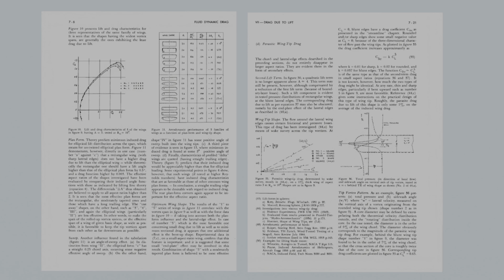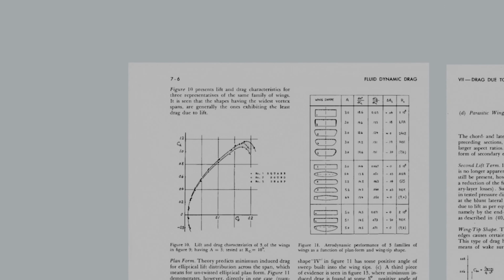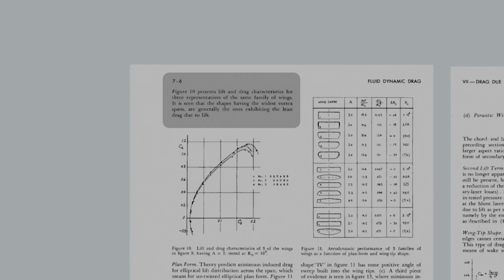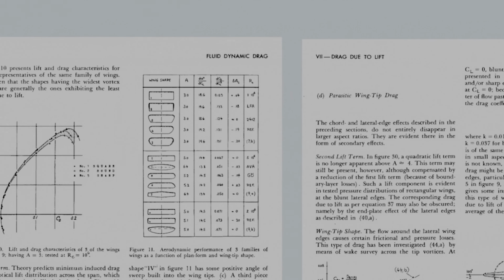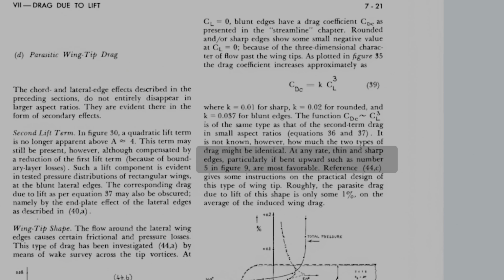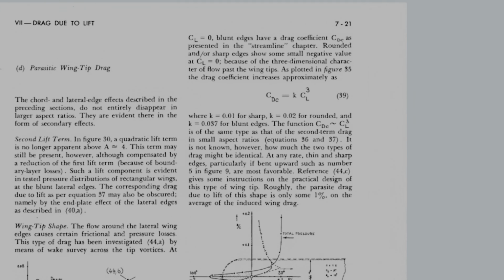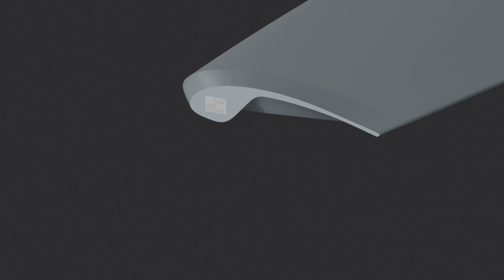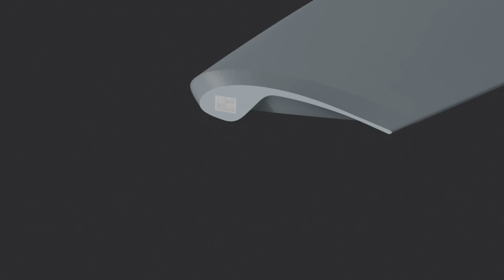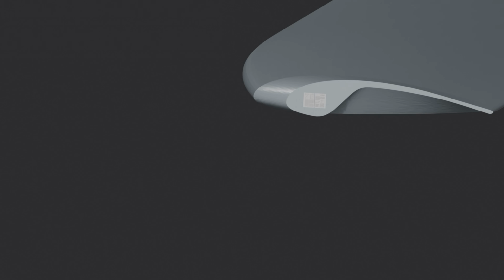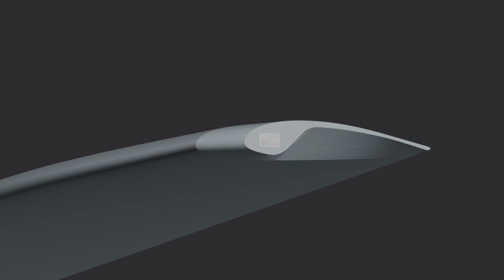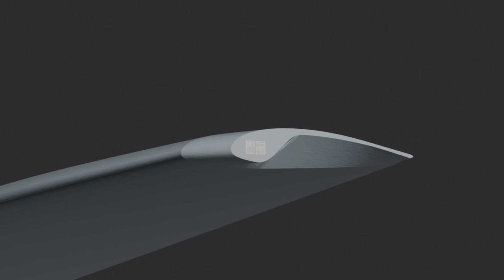After reviewing the geometry of the CAD model, I found that the curvature setting of the wingtip chamfer transition area was too smooth, and there was significant bluntness on the lower side of the leading edge. This geometry directly weakened the forced airflow separation mechanism of the Hoerner wingtip configuration, preventing the airflow from achieving sharp separation at the predetermined location, thereby losing the core-induced drag suppression capability of this configuration, which directly caused its simulation performance to not meet expectations.